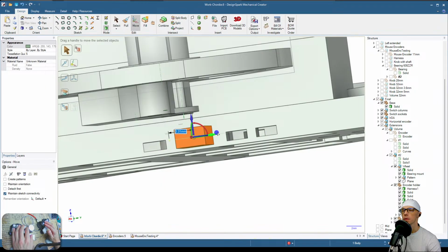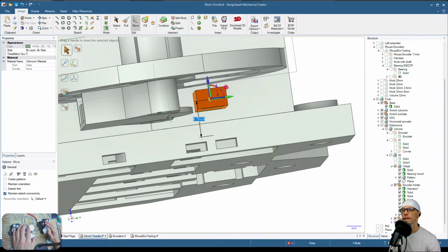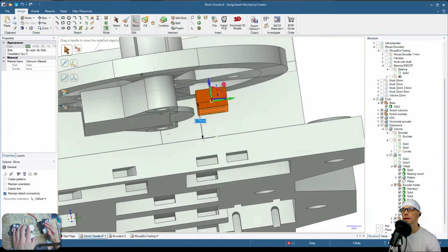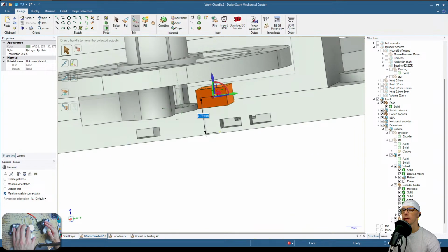Okay, what can we do about it? Maybe if we skip the margin that was 0.1 and we keep it like 2 millimeters, so basically the push button should be touching the top wheel all the time, and then just a gentle push should press it.